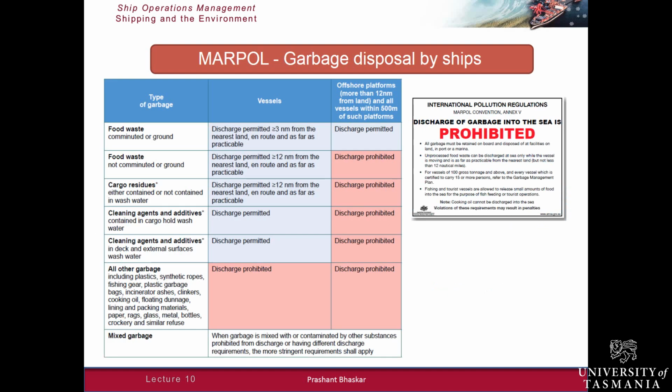Let's turn our attention to garbage disposal. This slide looks like it's very wordy, but it's actually very simple. The garbage disposal requirements under MARPOL. This slide summarizes the requirements for ships when they're outside special areas. Australia is outside special areas, so let's look at that. And essentially, what you can see is that there are requirements, first of all, depending upon the type of garbage, and secondly, how far the ship is from the nearest land.